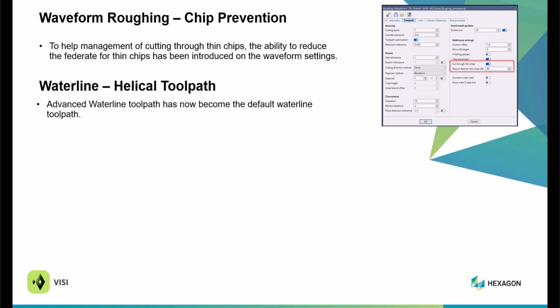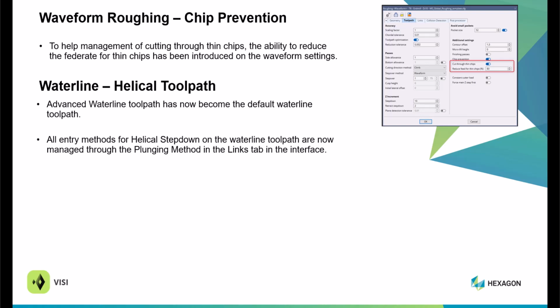Waterline helical toolpaths. The advanced waterline toolpath has now been combined with the default waterline toolpath. This allows for all entry methods with helical. The waterline step down is now managed through the plunging methods within the links tab.